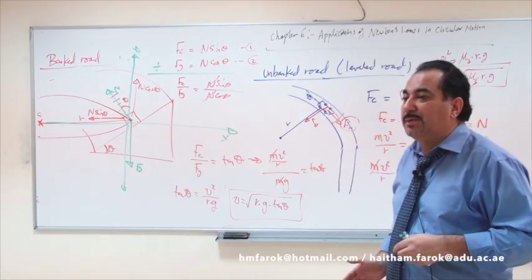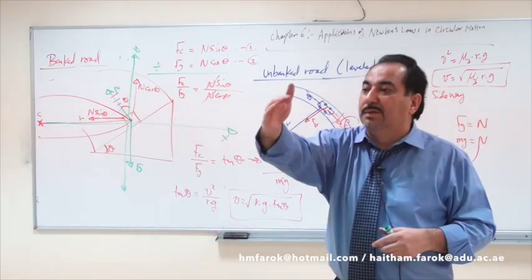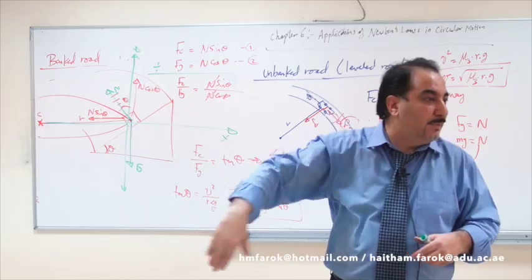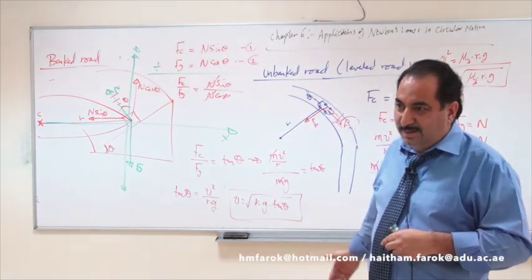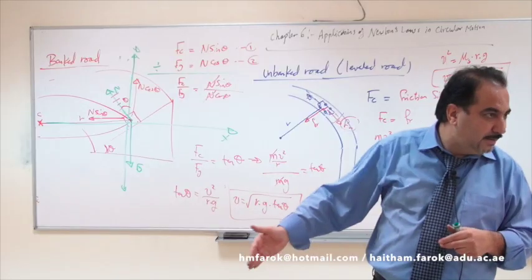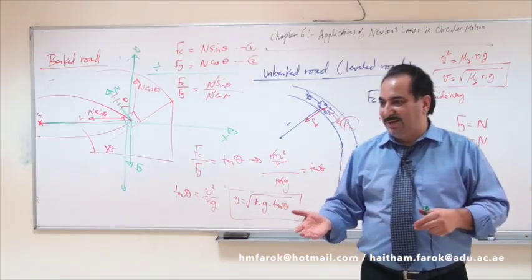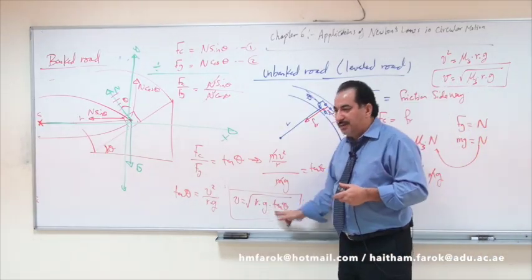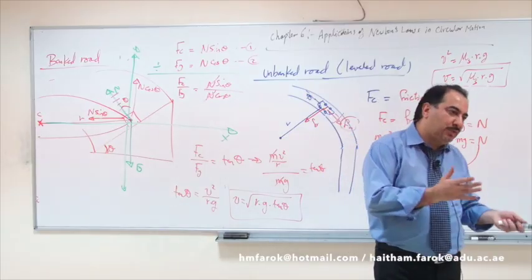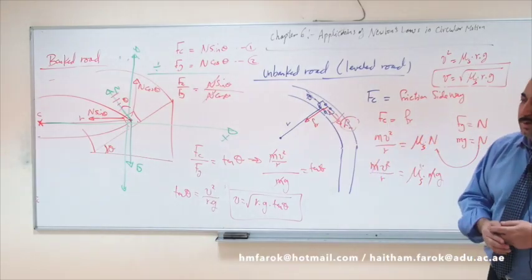Big radius means when you want to design the road, you have to demolish some of the houses, yeah? Big area, because you're taking a big arc. You're taking a bigger piece of land, and that costs money as well. So it's a balance between those two factors. Think of these two in your design. Which one is more suitable, doesn't cost that much money.